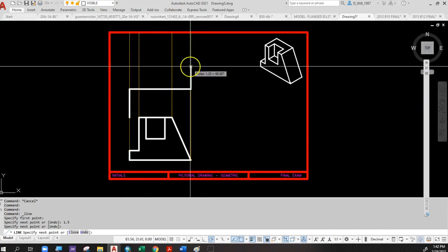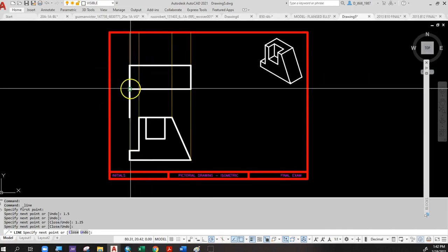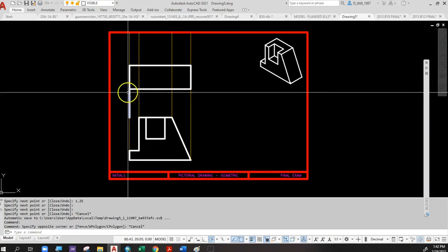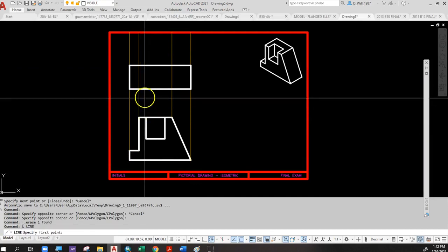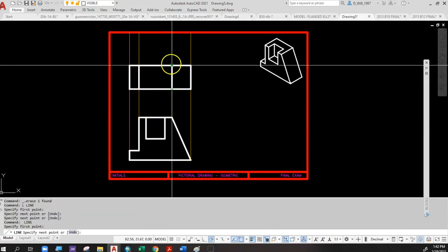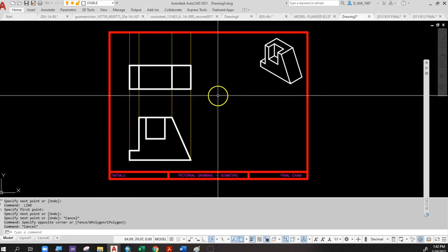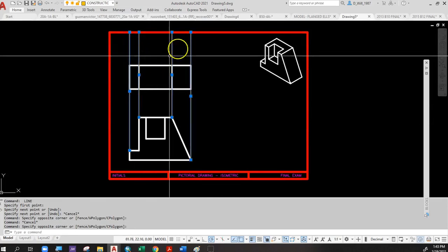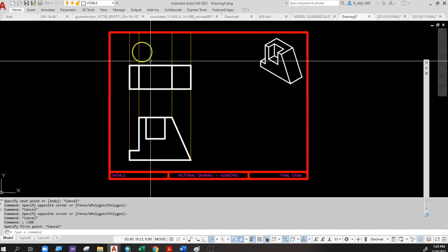But what I'm doing is I'm trying to draw my top view, and I'm going to use all of these construction lines to lay out where things are supposed to go. You see, I'm going to know now that I need a line here and here, and a line here and here, because I've got some light construction lines here. Right, so if we were doing this with pencil, you'd be drawing these things very lightly, projecting the corners up to be able to create the geometry in that top view. You would probably do the same thing, going sideways.